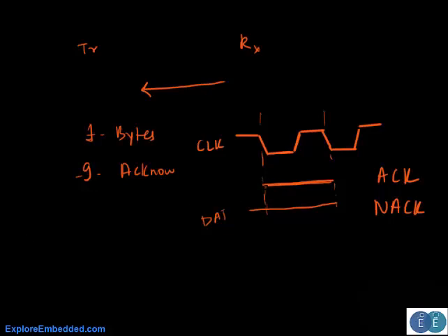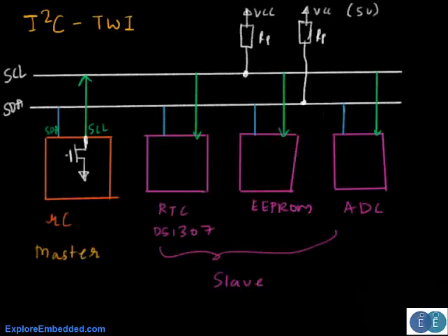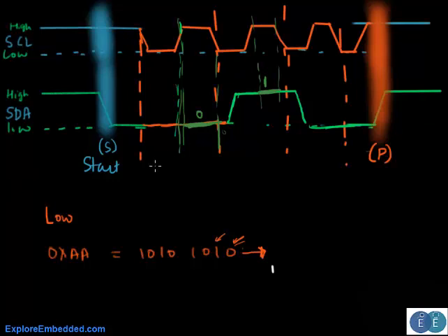So basically we have the start condition, the stop condition, the repeat start, the positive acknowledgement and negative acknowledgement. These are the basic things that you need to know before interfacing I2C devices. Now if you're using a device with 3.3 volts, you need level converters, and if the device uses a 10-bit address instead of 8-bit or 7-bit, then we need to consider a few more things. But for now, if you're using a 5-volt device working on 7-bit addresses, this should be sufficient.